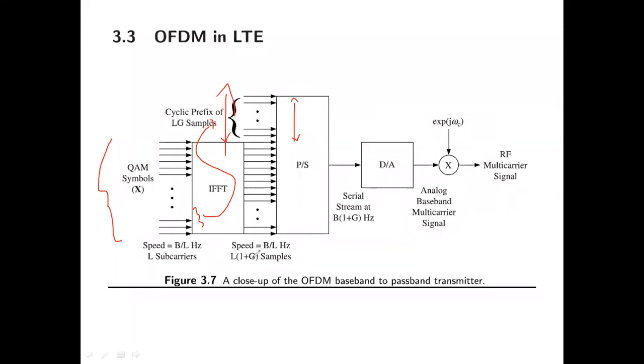It is based on G, related to the guard interval, how many additional bits we need to take. Two things: to take care of the guard band, and then to get the CP. What should be the actual length of CP? Because a larger CP length introduces the rate loss that we discussed in the previous class.